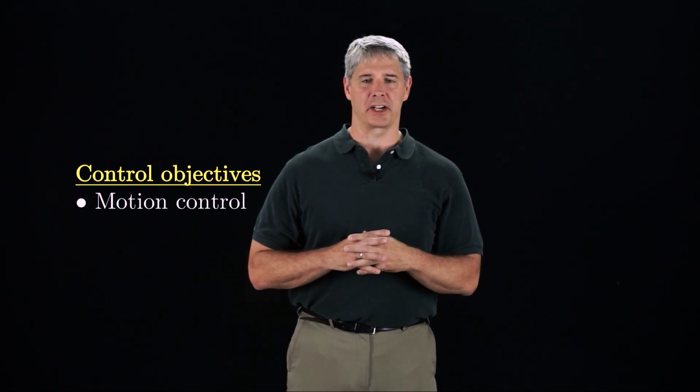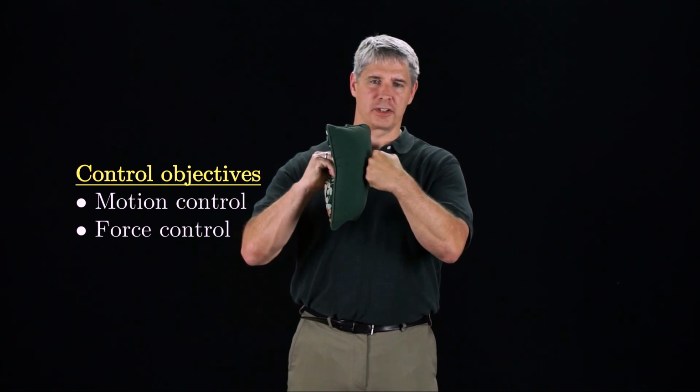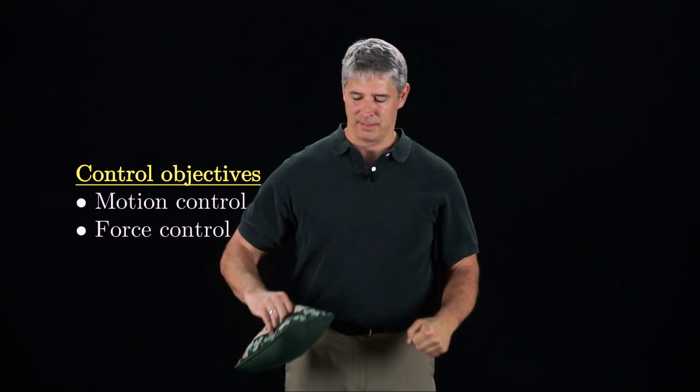Every robot has a controller which continuously reads from sensors like motor encoders, force sensors, or even vision or depth sensors, and updates the actuator commands so as to achieve the desired robot behavior. Examples of control objectives include motion control, as when a robot arm moves along a specified trajectory. Force control, where the objective is to apply specific forces to an object or the environment.